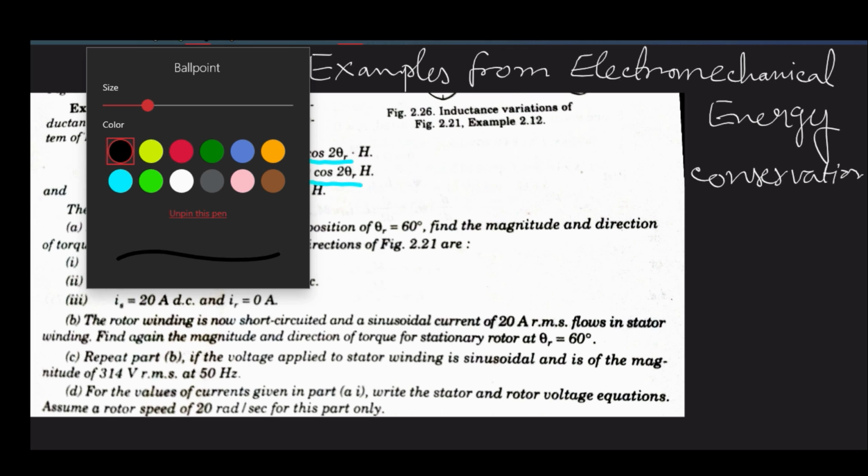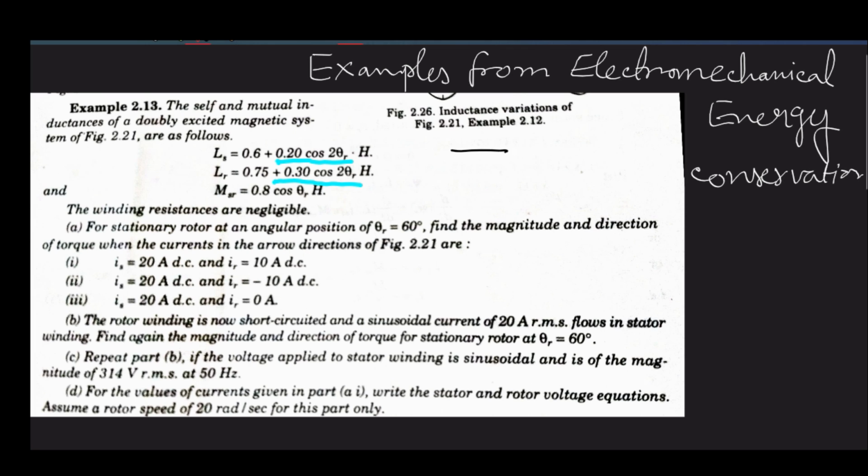if you have something like this, more or less a round rotor that is symmetrically placed, then you will find that the LS and LR terms will not contain entries that are twice the rotor angle, right?